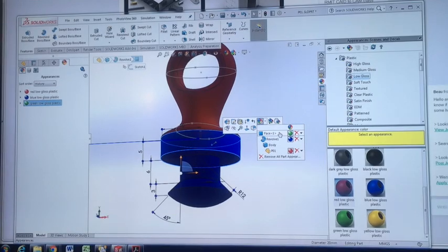So when you're doing your rendering, and if you're applying to a SolidWorks part that you've built, if you had like a text cutout into a surface, let's say the entire surface was like a satin finish material, and then the cutout was a gloss, you could just drop that gloss material onto that cutout feature and just say apply to this feature. Okay, and it would do all the cutout faces. You don't have to select them all individually. So that's why SolidWorks is good for adding materials in.